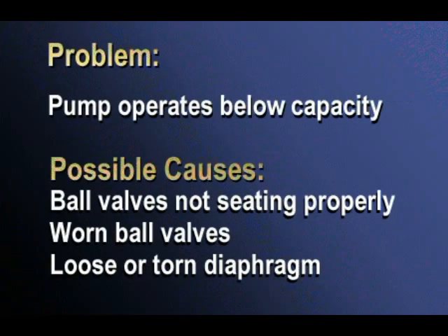Problem: the pump will not pump at all or pumps below capacity. The ball valves might not be seating properly. Clean debris from them or replace worn parts. Also, the diaphragm may be loose or worn. If so, tighten the bolts on the clamping ring or replace the diaphragm.